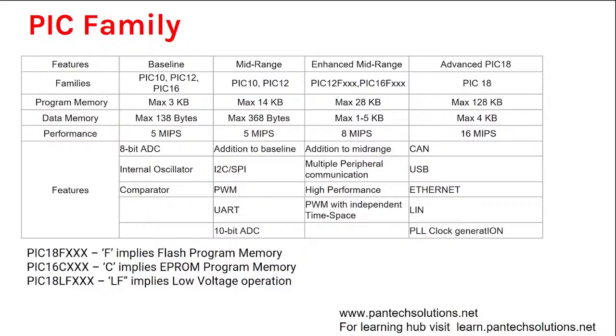If you check the mid-range, it has I2C, SPI, PWM, UART and 10-bit ADC. Okay, whereas in 8051 it does not have an inbuilt SPI or I2C. There is no register for I2C or SPI, but this mid-range PIC microcontroller has I2C and SPI, whereas the enhanced mid-range has the things covered in mid-range, plus it has high performance and PWM with independent time base.